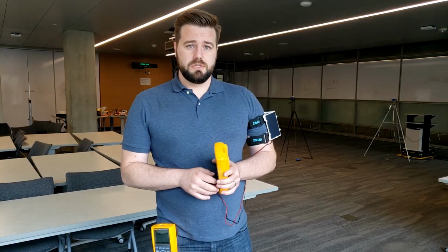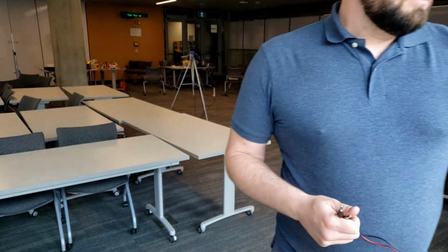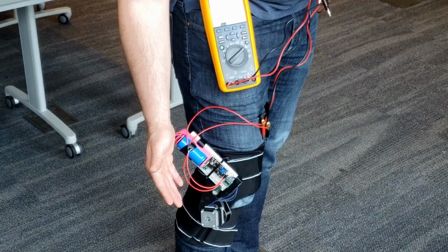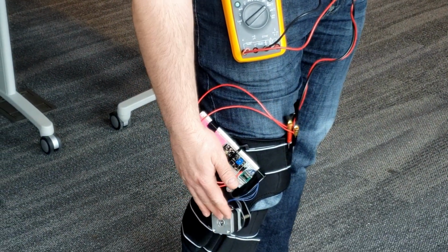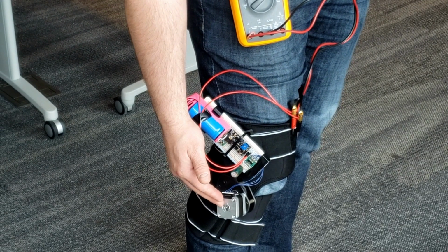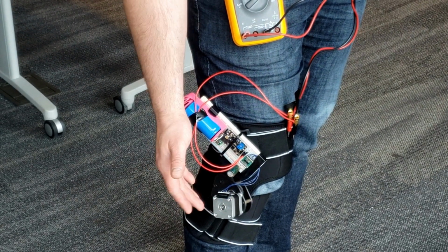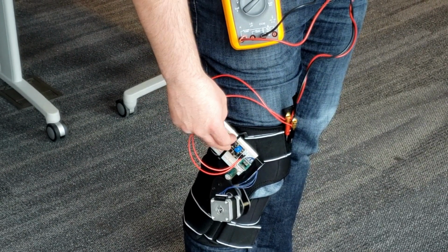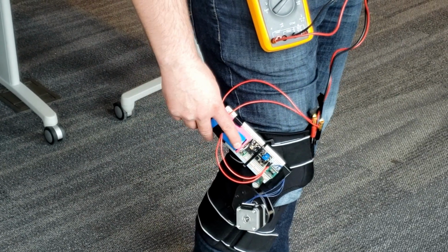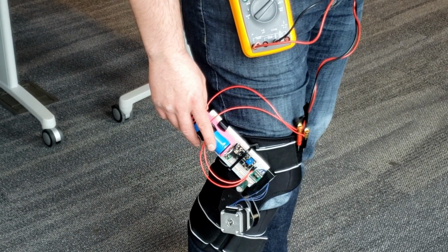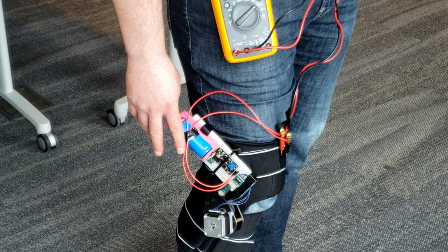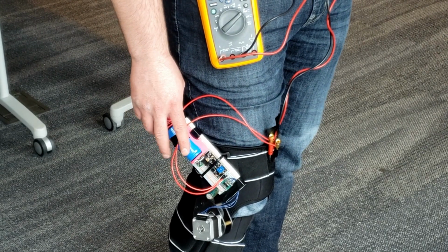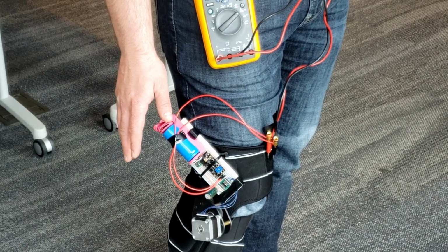And the more complex of the two units is the electromechanical harvester. And it is shown here on my knee in a very interesting way. Now we have a bipolar DC stepper motor here, which produces a DC square wave. I should say an AC square wave of DC values. Here it's rectified in 2 stages because it is bipolar. And then we go to another lithium charger, and of course we have a lithium battery here. This is a lithium iron phosphate battery, a type of lithium chemistry, 3.3 volts nominal. More importantly, it's a little bit safer to wear because it does not have thermal runaway concerns compared to most lithium chemistries.